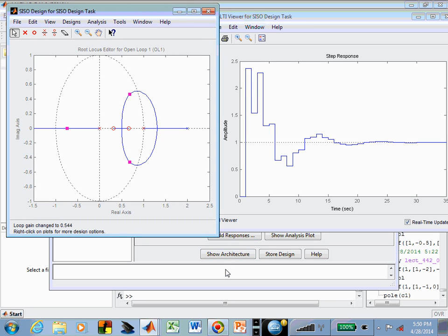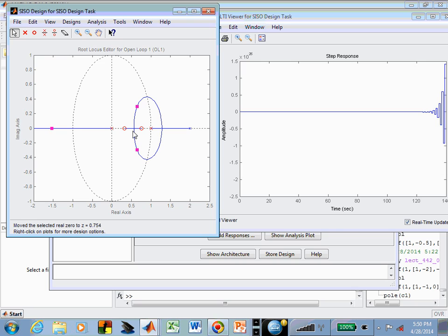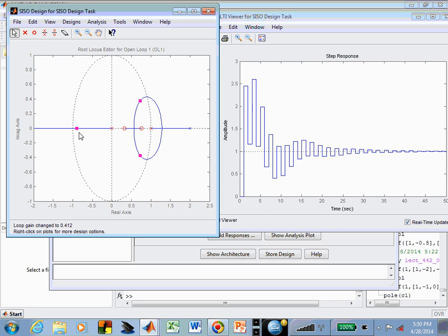And now what's sort of fun is you can start to, in real time, adjust these and have those step responses respond. But by pulling that 0 over, my gain has been adjusted to where now it's driven that pole outside the unit circle. That's maybe not a good thing. If I put it here, maybe that's not so good, but at least I'm stable.